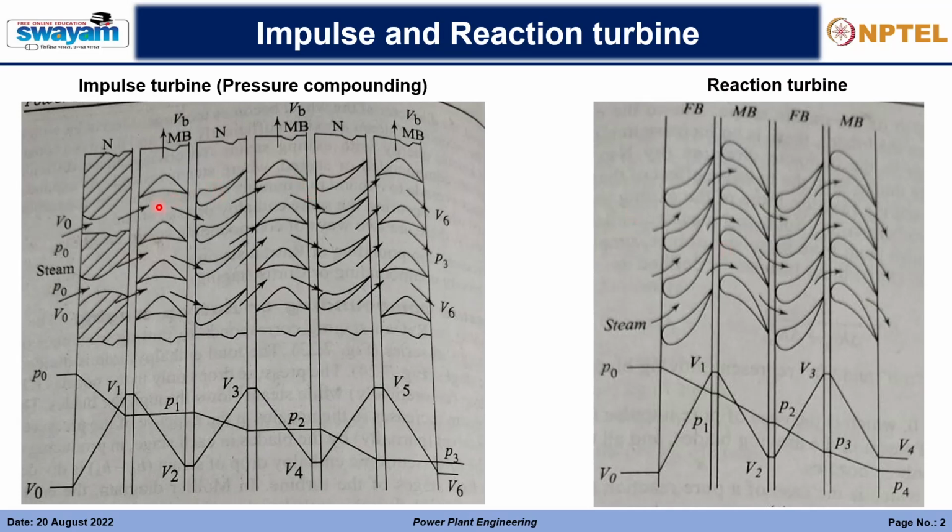So you can see that here the steam is coming inside the blade, right, like this, and the relative velocity outside is moving backward, but the blade is moving in this direction. So for this we'll have to subtract the value of vb to get the vr1, and here we are already getting vr2 but it is in this direction, so the net velocity that is tangential to the blade is vr1 minus vr2.